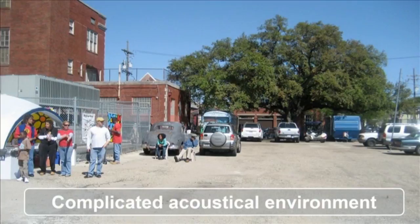So we have pretty good methods for accounting for reflective surfaces located directly behind the equipment, but reflective surfaces in other locations are more challenging. Examples of these include other buildings, solid fences, and other pieces of equipment. Think of a courtyard. This photo shows a real-world situation that would be more difficult to model. Here, the reflective surfaces are not very tall, and the chiller's kind of in a corner, but not really, and there are many other reflective surfaces. This is pretty far from the flat plane used to calculate reflection and warrants additional caution.